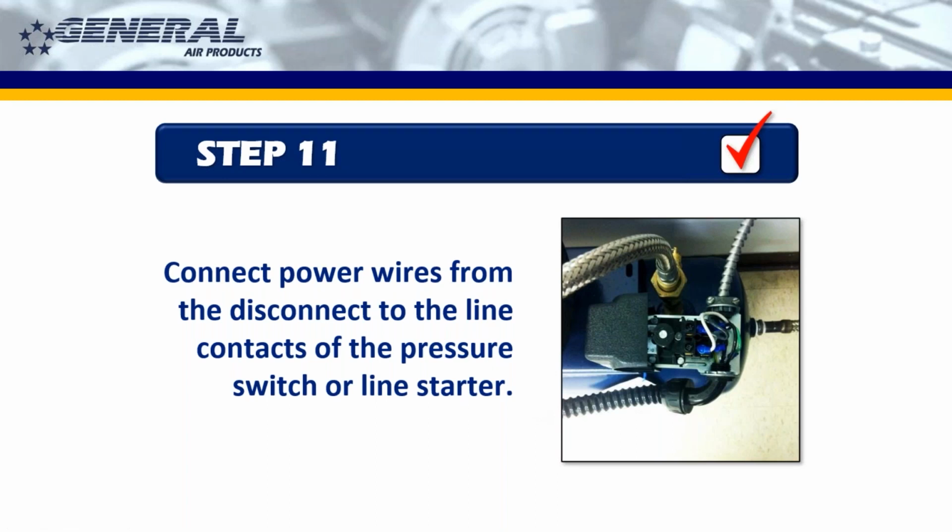Then you want to bring power from the pressure switch to the industrial disconnect. That would be the next step. And again, this is usually the electrician doing this, but if you know these steps, you can watch them do this and make sure that they're doing it right.